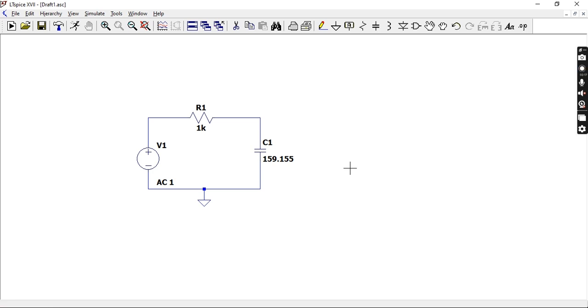So with this AC analysis, you are able to see the frequency response of your circuit. Just like we did when we covered DC sweep, where we were stepping through voltage values, you're able to see the behavior of your circuit as you change the voltages, from a low voltage to a high voltage. The same applies in the frequency domain. You can actually see how your circuit behaves by setting a start frequency and a stop frequency. And the output of that is called a Bode plot.